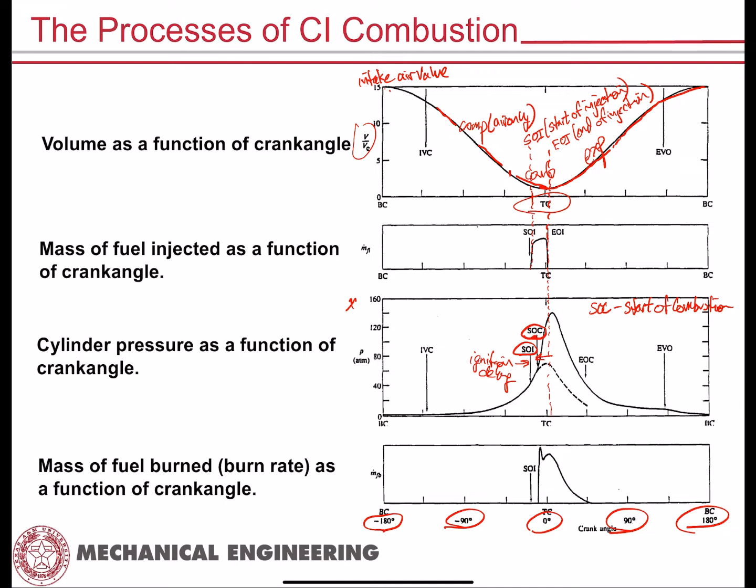So if I follow along here on this pressure curve, we've got the motoring curve, right? We're just compressing air, motoring. And if I didn't inject fuel, then my motoring curve would continue in this dashed line fashion. So I'd compress, reach top dead center, reverse piston direction, and then expand the volume. But I am injecting fuel, right? So now my cylinder pressure rises, and then combustion begins. So now my cylinder pressure rises due to combustion, right?